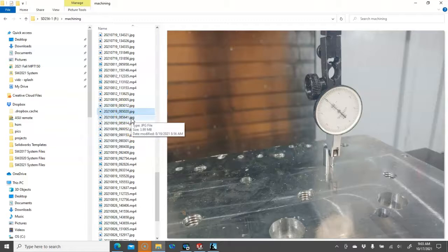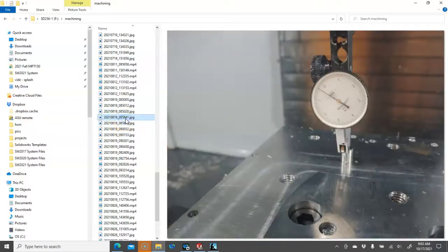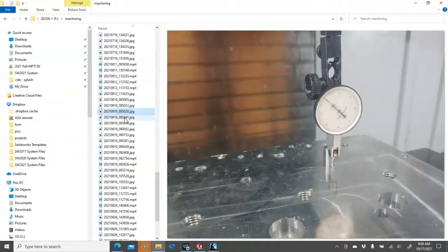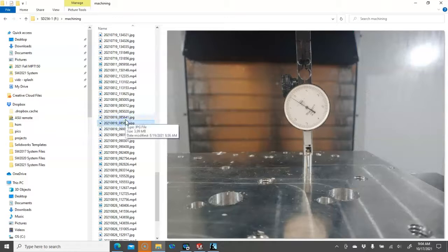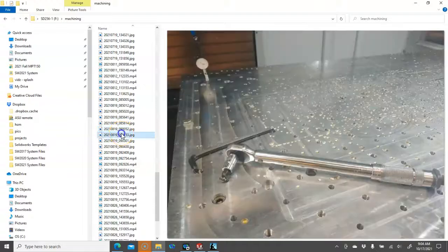And then we put a dial indicator on it, and this is a 0.0001 indicator. So 1/10 of a thousandth for each of the small marks. 0 to 1 is 1/1000th of an inch, and the total range is 16 thousandths, I believe, 8 thousandths in either direction. So we run it back and forth. So 0 there at the high point of the pin, and that is within 4/10 over 60 inches. So that's pretty close. And then we tap it a little bit and go back, and now we're within 2/10, and tap it a little bit, and legitimately we can say it's within 2/10.